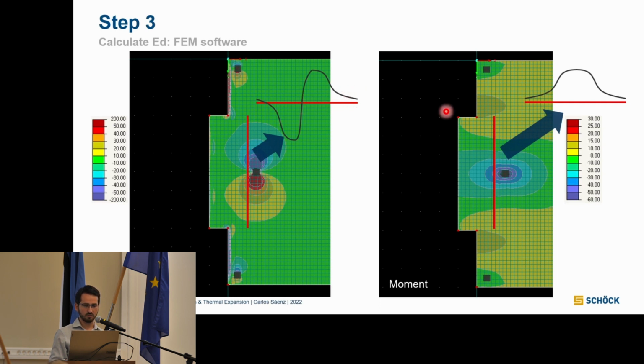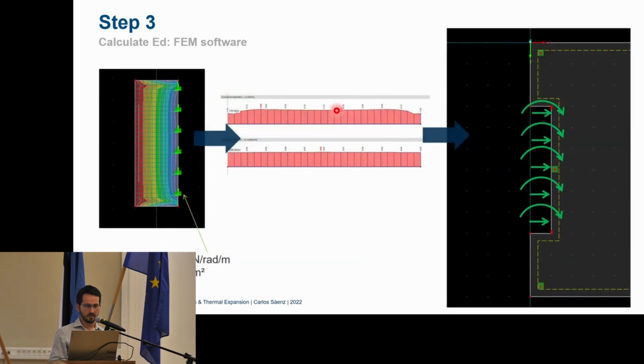And yeah, right click and show me the diagrams of the forces. And the problem with that is, you get to see the results here, for example, for moment. This is the diagram for moment. You get to see values from 0 to 10, let's say, in this area, on this side. And I will point out the risk of proceeding this way, because if you consider those are the forces acting on your thermal break system, and compare it with the good design, you will notice the difference. So here's how you are supposed to do it.